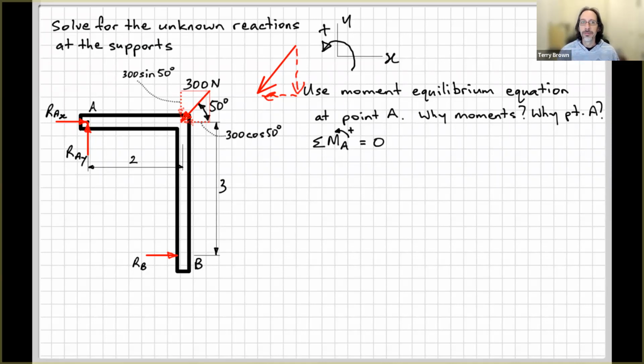I tend to avoid doing that because if you take this vertical component and put it over here, it looks like it's acting further away than 2 meters from point A. So it's not strictly correct in terms of defining where the component lines of action are. If you're used to drawing components of forces like this, try to sometimes draw them like this, just to get out of the habit of drawing it without thinking about it.